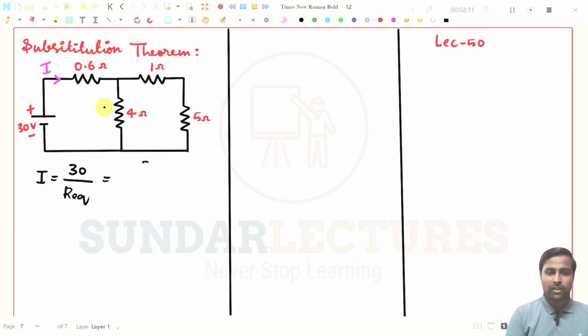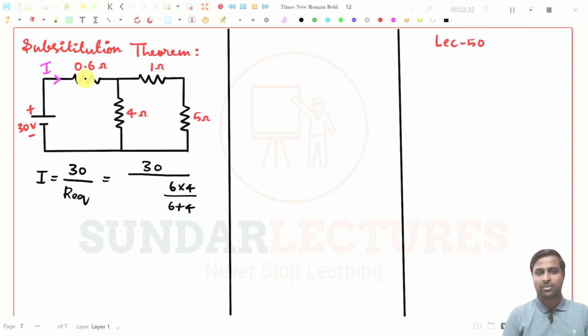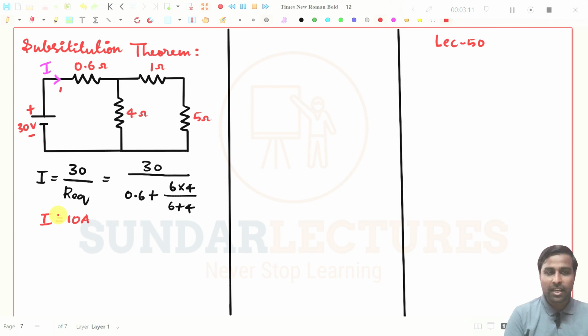If you simplify this, you will get a single resistor. So I put 30 divided by, these two are connected in parallel, 6 ohms and 4 ohms. So it will be 6 into 4 divided by 6 plus 4. Then you will get a single resistor, and these two resistors are connected in series now, so plus 0.6. 6 into 4 is 24, divided by 10, which is 2.4. 2.4 plus 0.6, you will get 3. So 30 divided by 3, it will be 10 amperes. So I is equal to 10 amperes. Here we are getting 10 amperes of current.